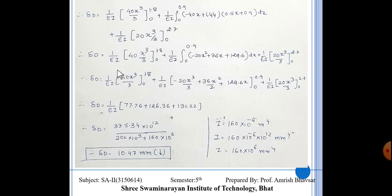So what we are going to do over here is put the values of E and I. I is 160 into 10 raised to minus 6 meter raised to 4, which we have to convert to mm raised to 4.